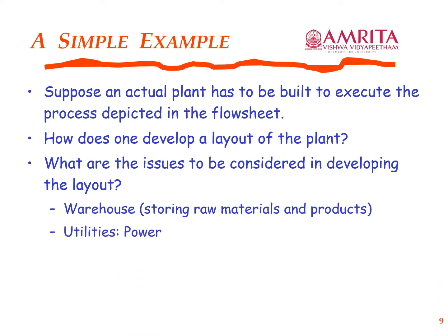Where is your power? Are you just drawing power from the grid, or are you generating some power in your plant itself? What about steam? You have a heater, cooler. I didn't show all the units that would be there. You could need steam. You could need cooling water. So you may have to have some steam generators. You may have to have some chillers. Where would you put them? And you may need air if you have some sort of compression in pneumatic processes or whatever. You may need air as well.